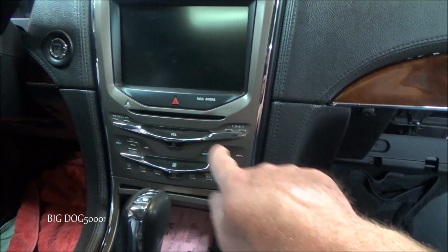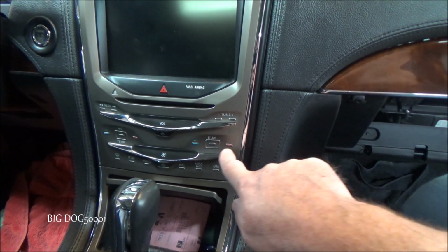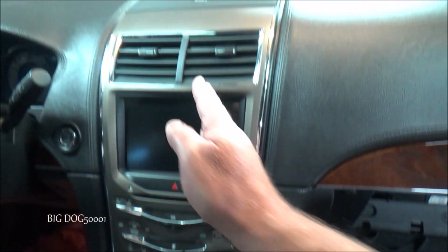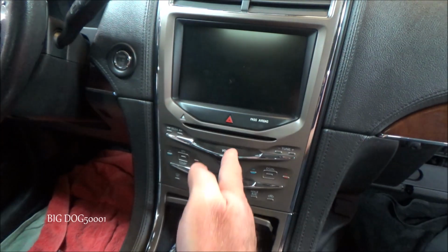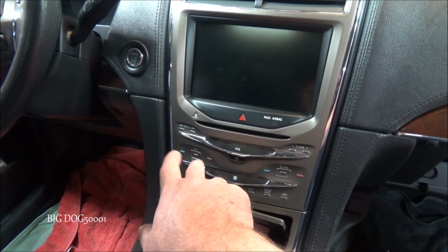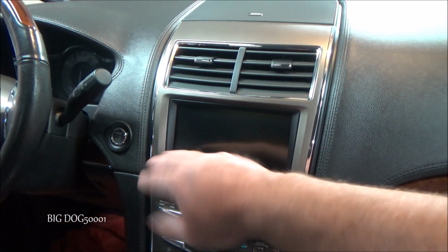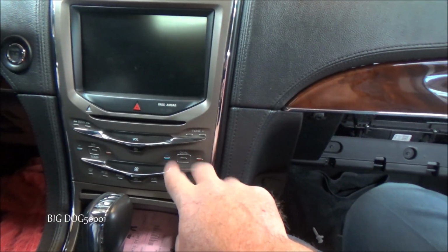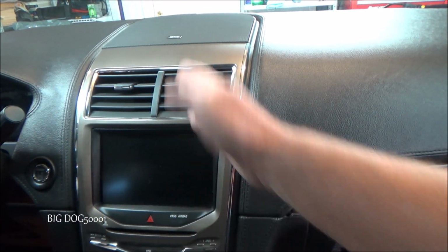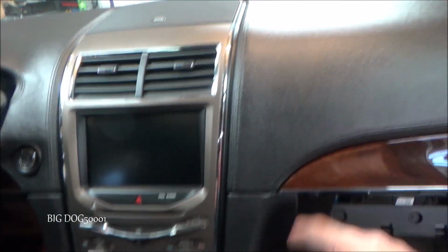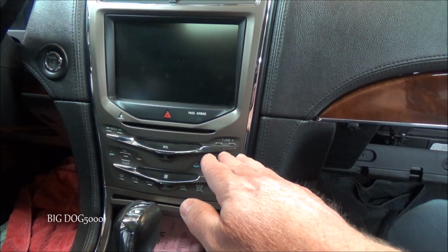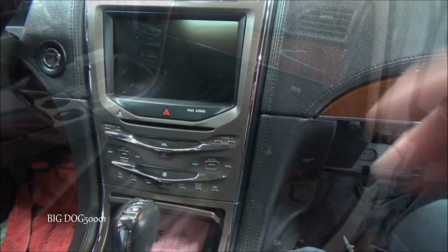But on dual climate control systems like this one, you can see we can control the passenger side temperature right here, and so that means our blend doors are going to be split right down the middle. So when we change the temperature over here, our blend doors are going to move inside there and change the temperature on that side, and vice versa. When we move the temperature over here, it's going to move the blend doors but only on this side over here. So it definitely helps to know, do I have a single climate control system or do I have a dual zone?